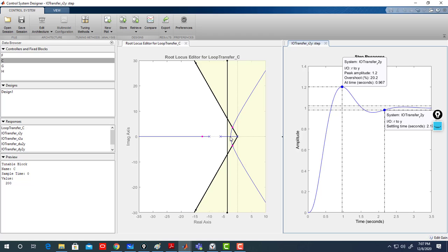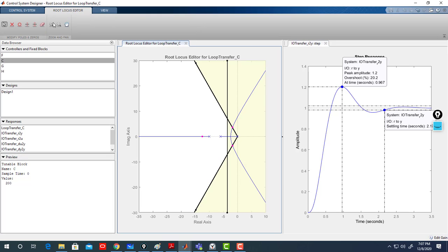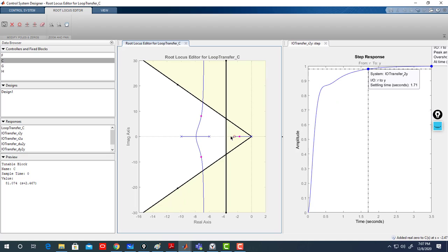So I prefer now to take a different design. I'll put it here. I click on it, so I find the editor one way, or you can double click and add it, or right click and add the zero as you wish. But I use this interactive way. I click the zero. Remember, it's a lead compensator, so the zero is close to the imaginary axis, and then I change my point. I fix my zero in here. See how it shifts my design.